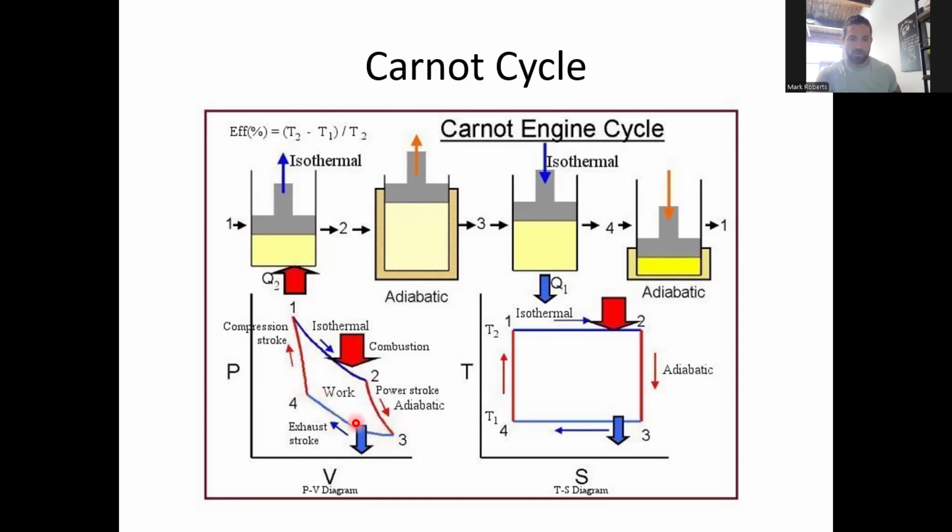So we would be adding work into the process, and then just finishing up the final compression stroke as the system is isolated as we remove the cooling from the process. From here, the integral of PV on the top curve is going to be our positive work, and the integral of PV on the compression side is going to be the work that we're doing on the system. So if we integrate in this area, we can get the usable work that can be accomplished through this process.